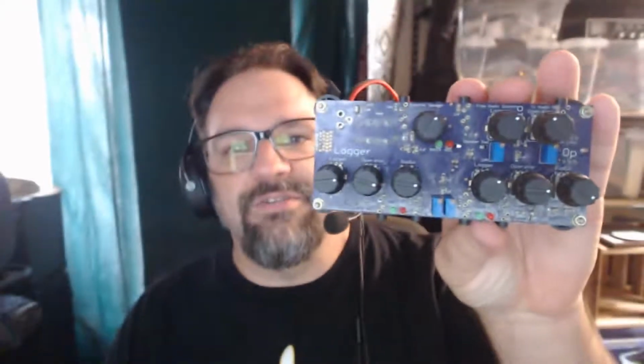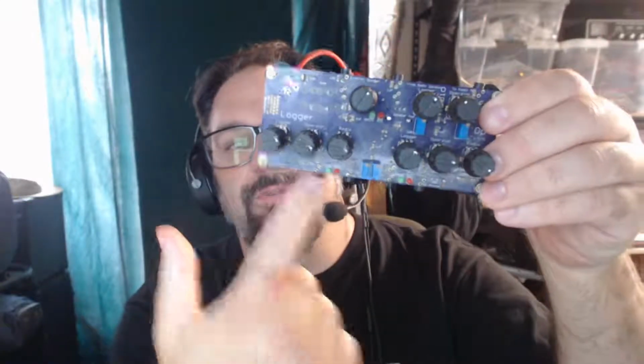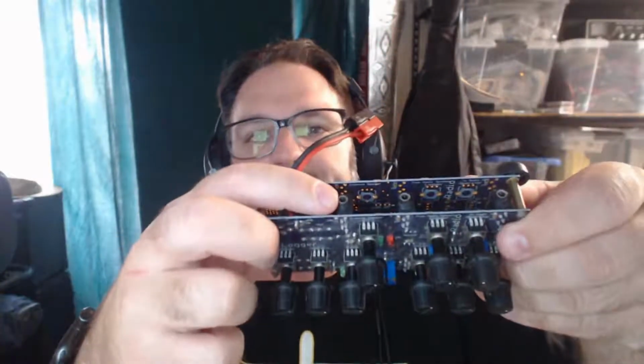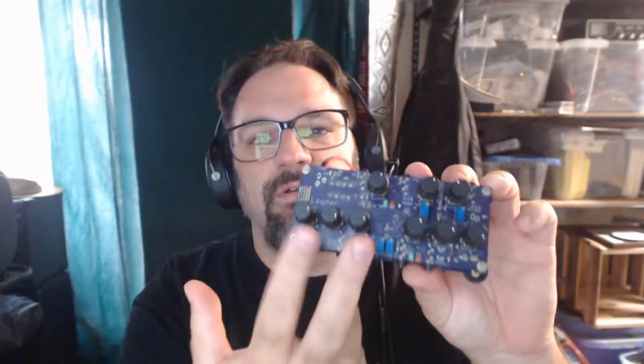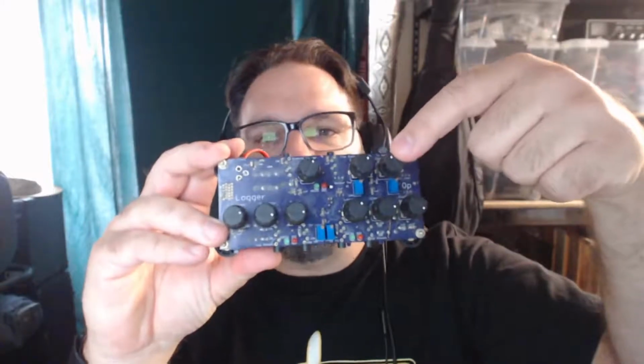The other board I was thinking of doing is the studio console, or the station console. This is not quite the same station console as what George is talking about on the Ham Radio Workbench podcast. This is more for contesting. I've talked about this several times on my stream, but basically it's got two ports for headsets, like PC gaming headsets, on the bottom, and then a couple of ports that go up to a radio, like a speaker input from the radio and a microphone out to the radio, then of course power, and then it's got little mixers. So for each of the two headsets, you can mix how much of your own audio, how much of the other person's audio, and how much of the radio audio you get into your headphones.